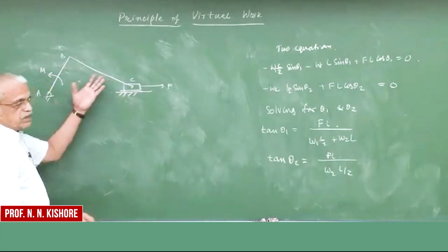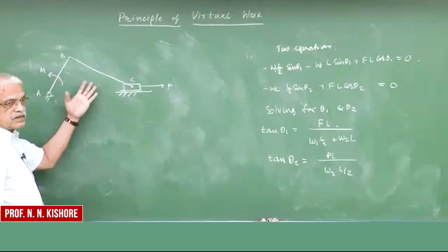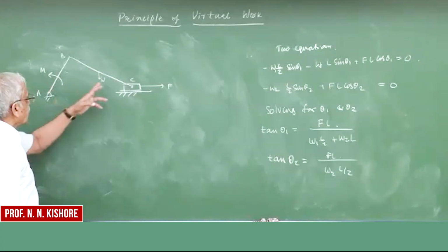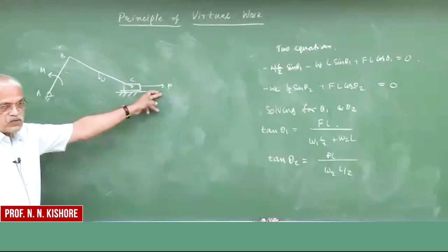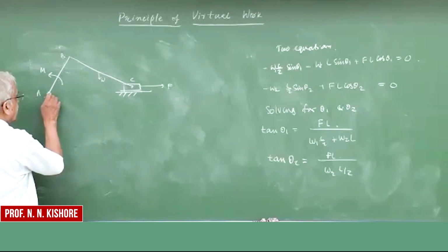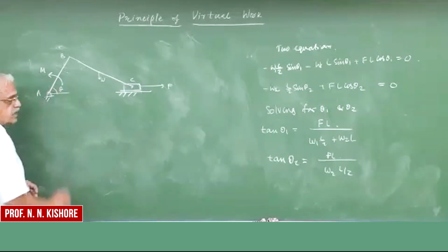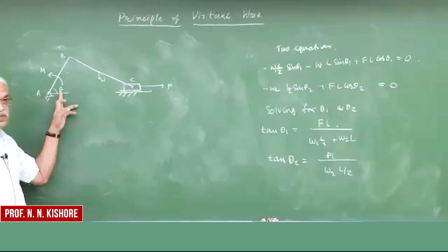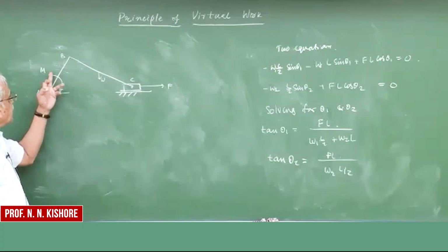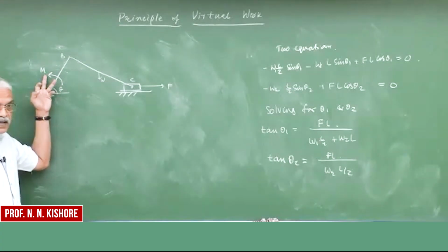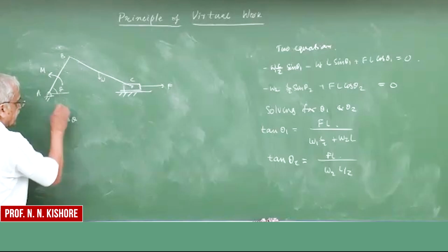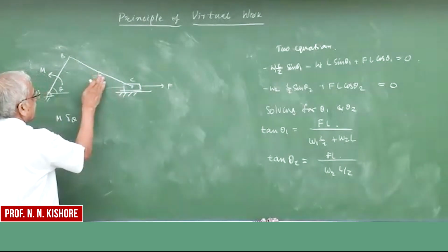It may be acted upon by weights, and you can also put a weight here if you want, or anywhere. These are three external forces, including the moment as an external force. If you represent the crank angle as theta, then a small virtual displacement of this degree of freedom, delta theta, will definitely cause a work contribution by the moment M. So the work contribution here is M into delta theta, and leave this alone.